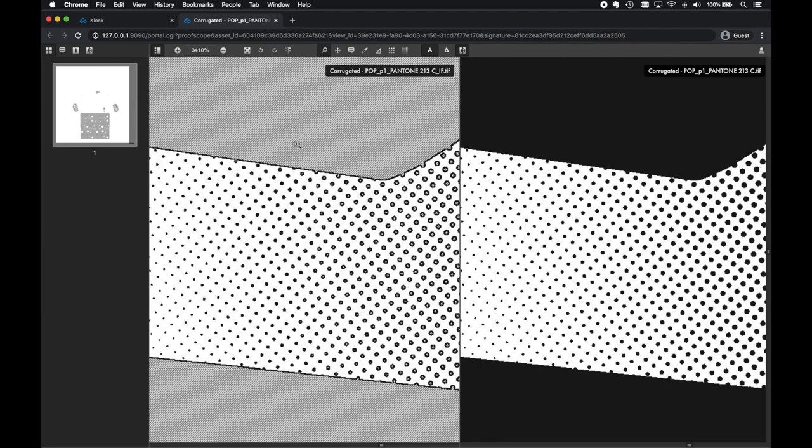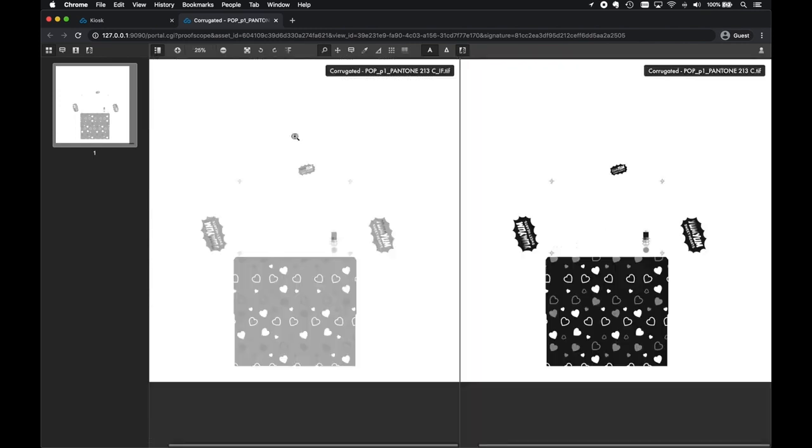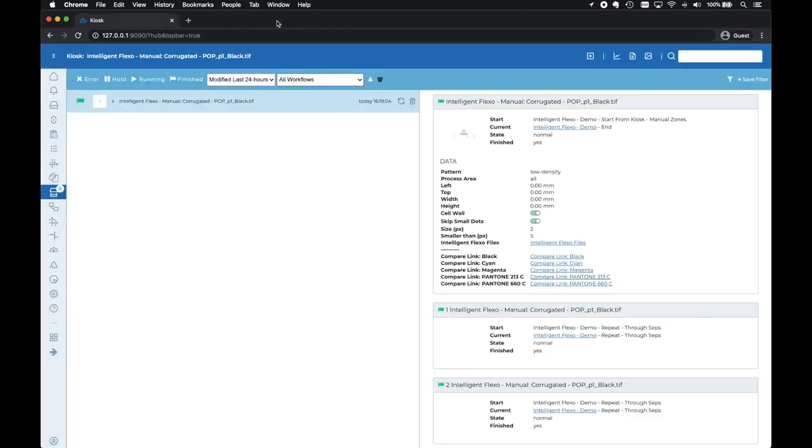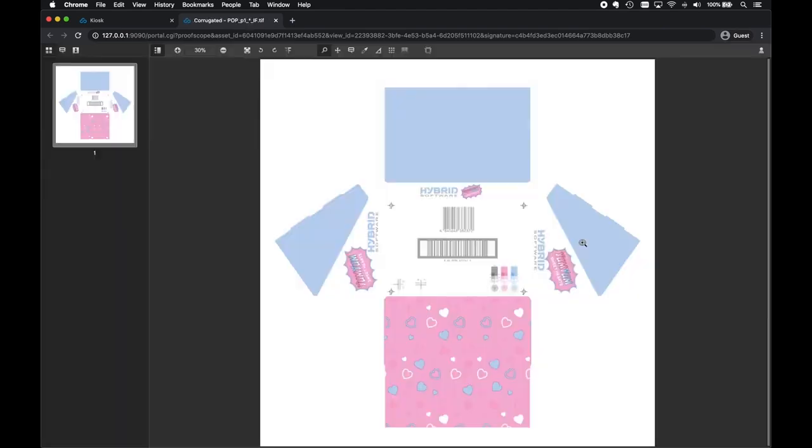With this patterning, this also allows even distribution and transfer of the ink, which will reduce pinholing and voids. This also has other effects like when working with barcodes, we can reduce trailing edge void on the horizontal bars. We're actually going to inspect the file in full color now so we can see the full design. So we can zoom into, let's say, the barcode down here.